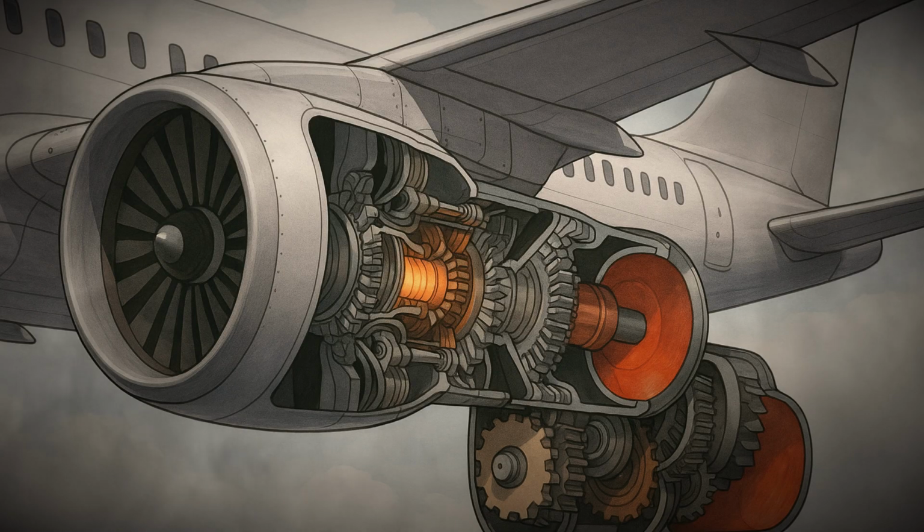Lift is not only about keeping an airplane aloft, but also about maintaining stability and control. Engineers design wings with specific twists along their length, a feature known as washout, to ensure that stalls occur at the wing root first, preserving aileron control near the tips. This makes the airplane safer and easier to handle. Additionally, devices such as slats and vortex generators are used to improve airflow over the wing, delaying stall and increasing lift at higher angles of attack. These features demonstrate how deeply the principles of lift influence the detailed design of aircraft.